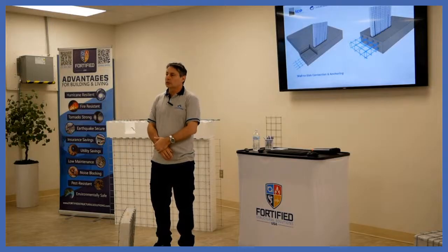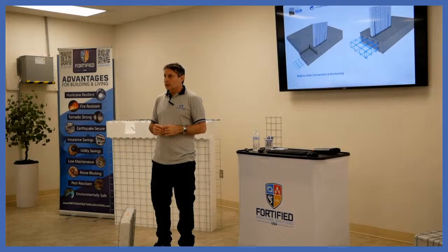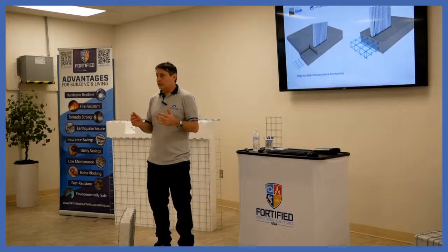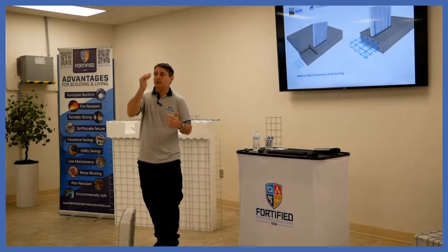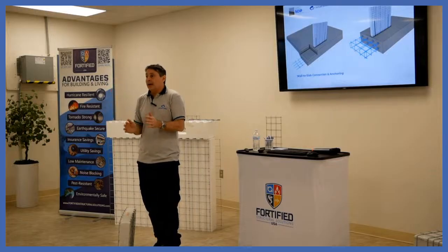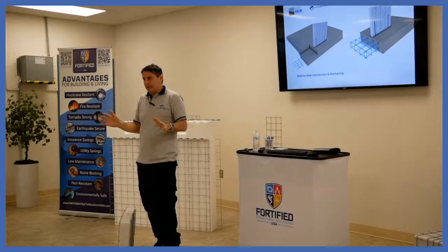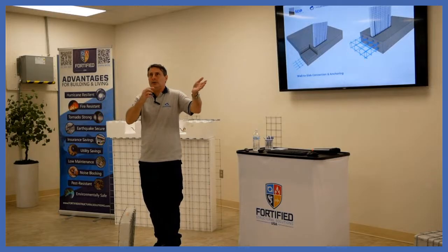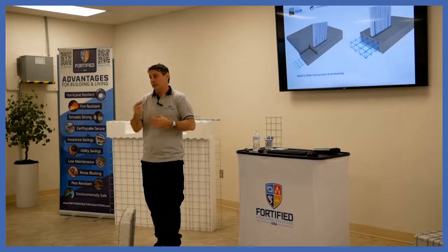So you usually have those tools available, or tables? Well, let's say for a 10 foot span over the slider, is there something I can use? 10 feet, as I mentioned, probably requires about 3 feet of header. About that 10%, then you have to dig a little bit more. I don't know about the other combinations, just to have something in mind.